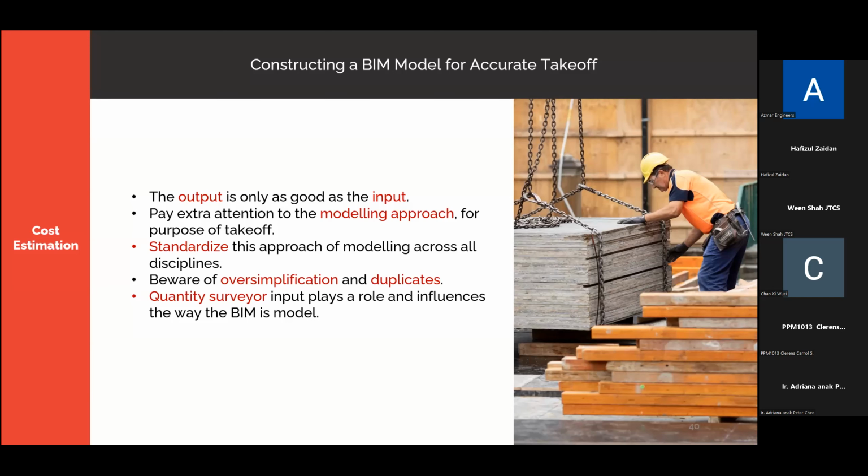If you apply cost estimation to BIM at any stage of the design, early stage at LOD 200, maybe 300, where LOD 300 is the accurate point, then 350, 400, 500, you can extract a very accurate material takeoff. You can either extract it directly from the BIM authoring tool to Excel, where the QS can build formulas upon it, or you can use many third-party software out there that can read the BIM model and automate the extraction, or automate the work of cost estimation.